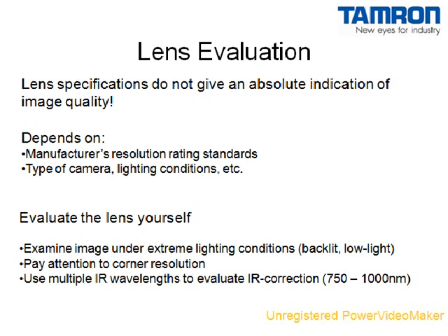Examine the performance of the lens in extreme lighting conditions. Pay particular attention to the resolution in the corner of the image. If you are evaluating a day and night lens, test the performance over a wide range of infrared wavelengths.